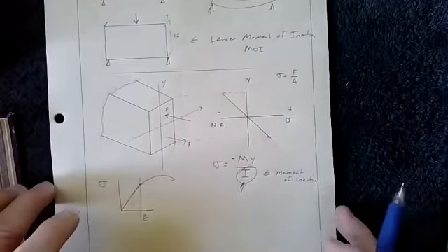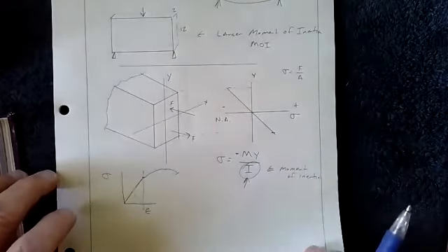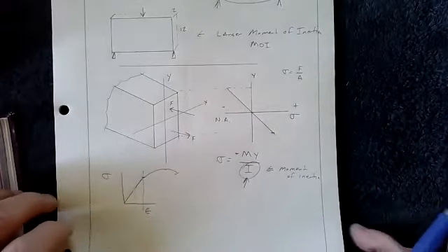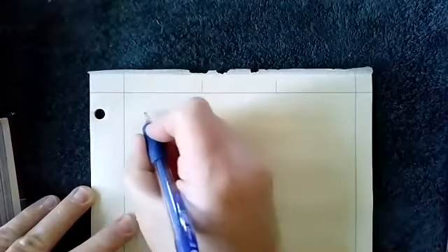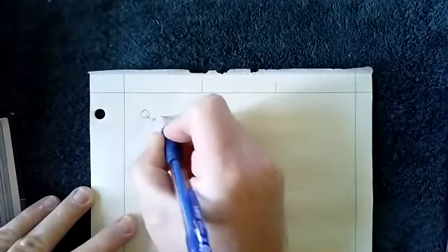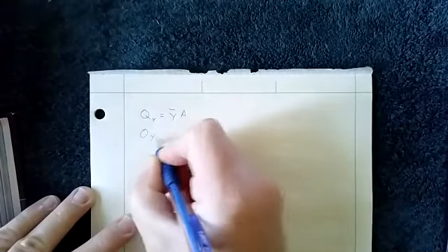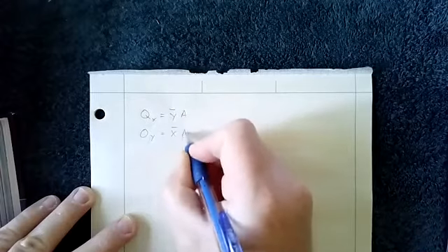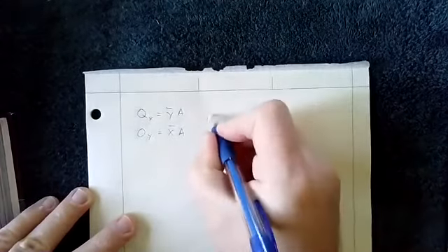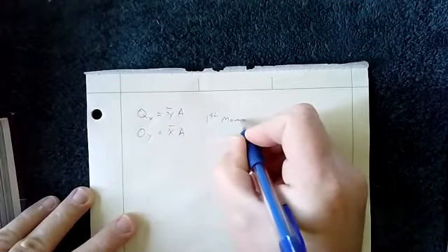It turns out that I can be calculated by integration, or you can use equations for typical geometric shapes, very similar to what you did with centroids. One thing we want to address is that you may recall in the reading on centroids this relationship: Qx is equal to y bar times A, and Qy was equal to x bar times A. And this was called the first moment of area.